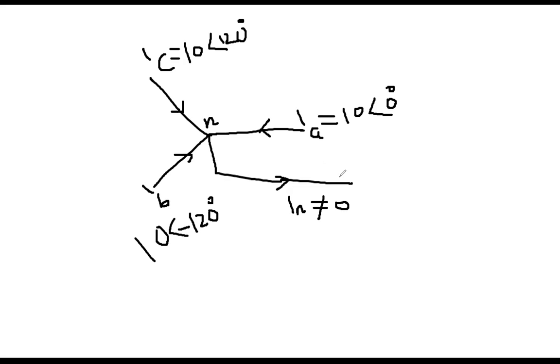Or even though it might not be burnt out, assume that it did not get burnt, but because current is flowing, for example, 15 ampere is flowing through this line. And because this is the neutral line, say there is another system, you don't know what the system is. This is a three-phase system and it has its own neutral line.